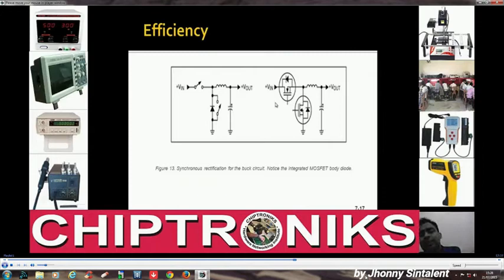As we have spoken, there are two types of regulators. One is asynchronous switching regulators, another is synchronous switching regulators. In notebook motherboards we have synchronous switching regulators. We are using two MOSFETs for a switch, but as I said, it's not necessary to have two MOSFETs. We can replace one MOSFET with a diode, but do not try to use that. If you understand what I have spoken till now, then you can do this, no problem. But if you're just understanding the crux, then do not do this. Just replace it with MOSFETs.